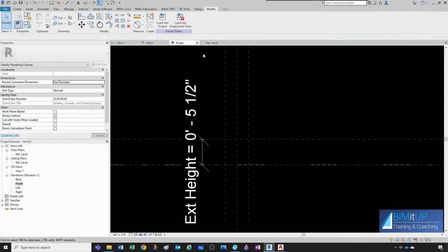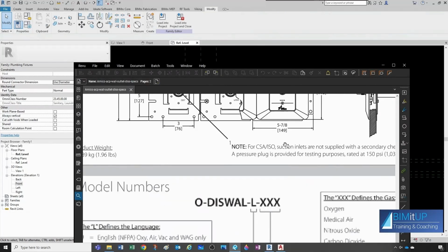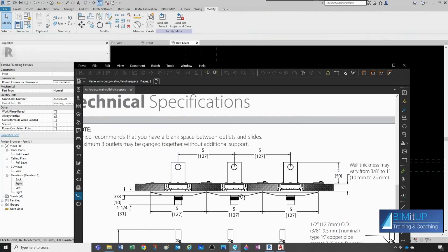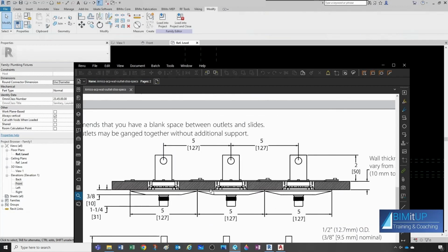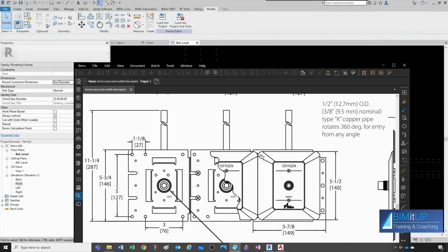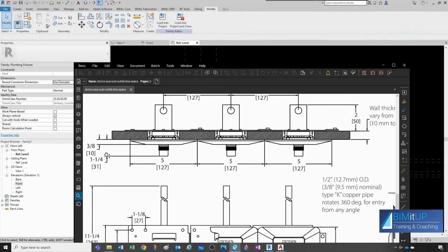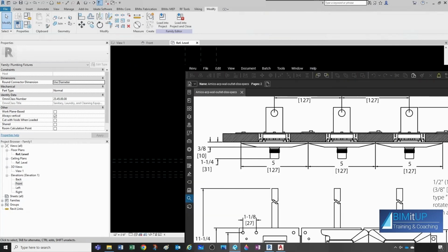Okay, now let's create our first extrusion, and I want it to start at the front face of the wall, right? And it's gonna be 3/8 of an inch. We already have these planes. We have the large profile of the plate on the wall, and then we have this small profile protruding 3/8 of an inch outside of the edge of the wall. So let's go ahead and do that. So we're gonna pick our front of the wall plane, and that's gonna be our first profile.